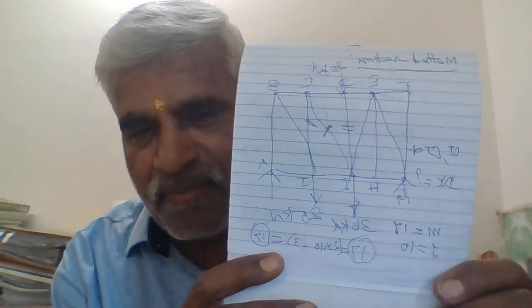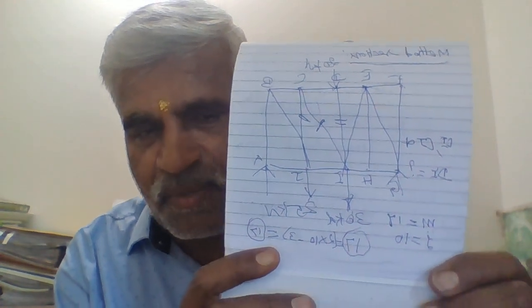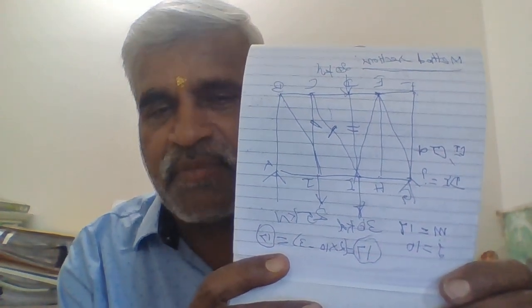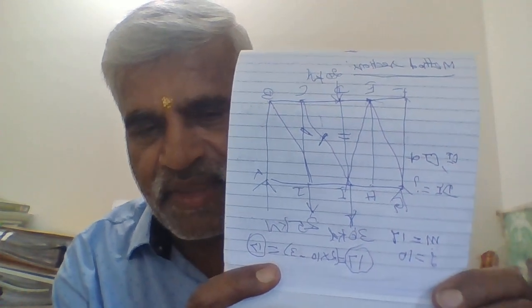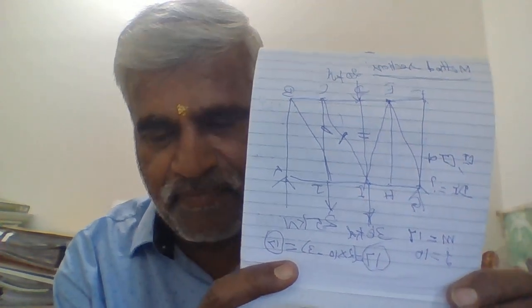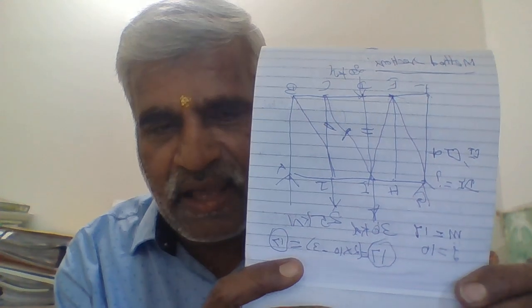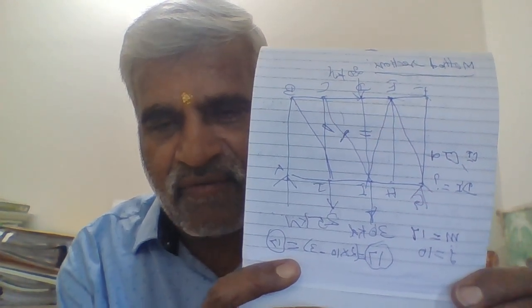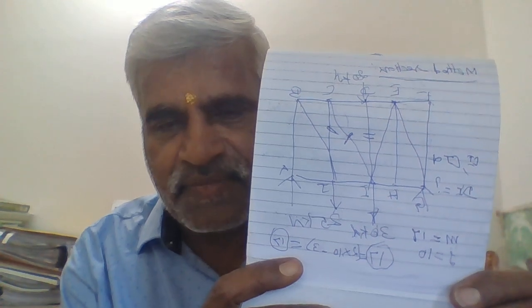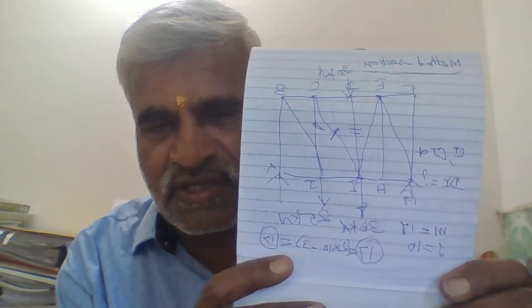So only three member forces have been asked. In the case of the method of joints you are also able to find them, but it will take a lot of time compared to the method of section. In the method of section, the three unknown forces can be determined very fast. For that, the method of section is very useful.